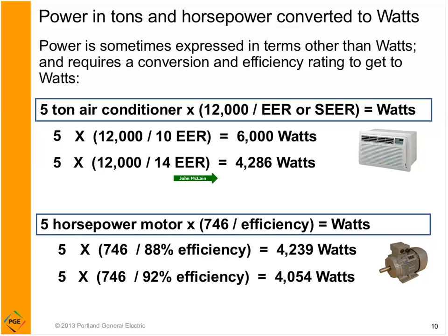The little formulas I've shown you today are very useful. This is a great little cheat sheet to kind of get that controlled. I had one business manager do a very good job of going around with a label maker and putting on all the pieces of equipment, here are the specs. If you have to replace this in the middle of the night or on a weekend or whatever, make sure the efficiency rating is at least this when you replace this unit. I thought that was a really good idea.